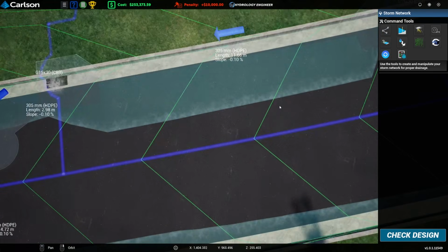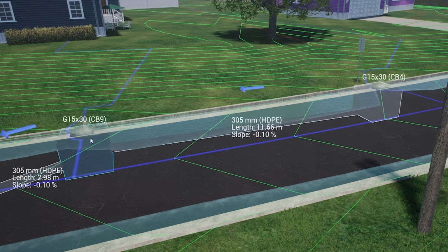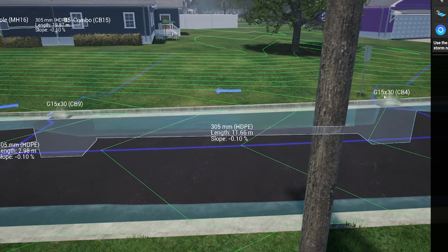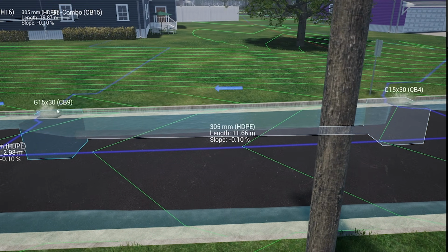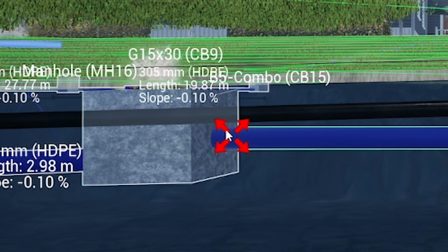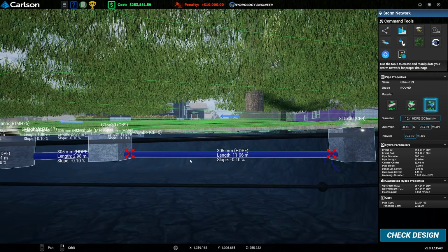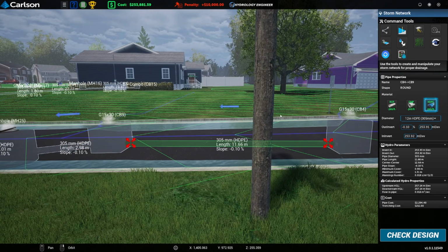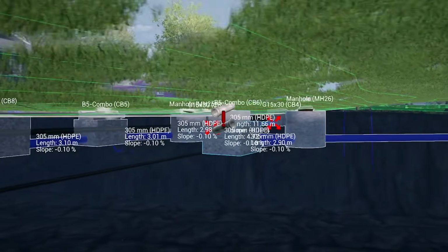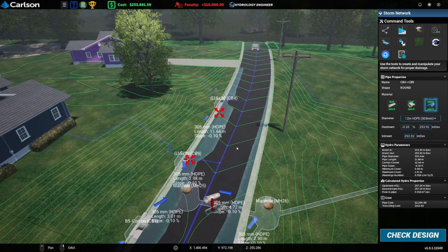Yeah, that is actually something worth noting. When you do daisy chain, you can't do it against the grade. So if you look at the surface levels, can you see they're falling from this way down to the left? So our pipe is also doing the same. Oh, actually, I don't know why that should be up in the air. But yeah, generally this pipe will follow the gradient of the surface. So you can only daisy chain if you're going downhill. Thankfully for all this, that works perfectly.